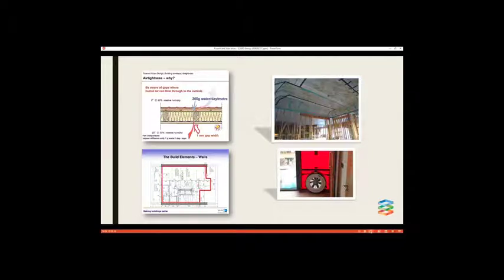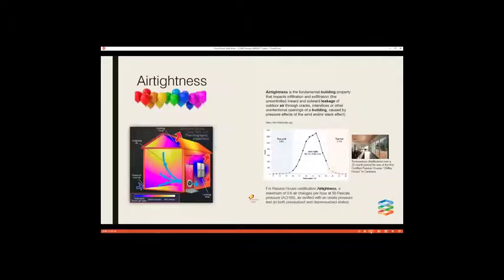The requirements for passive house are quite specific, and all of those final details are important. You're not just chasing one element, you're chasing a group of elements together to create a certified passive house. So the final test will give you at least 0.6 air changes per hour at 50 pascals. That's important. So an air blower door test, that was the red door image there.